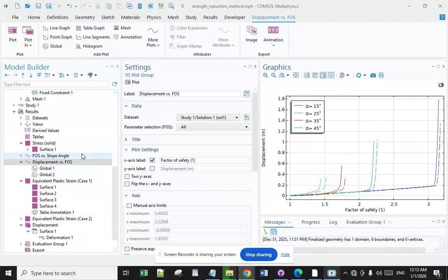Choosing design factors. Appropriate design factors are based on several considerations, such as the accuracy of predictions on the imposed loads, strength estimates, and environmental effects to which the product will be exposed in service, the consequences of engineering failure, and the cost of over-engineering the components to achieve the factor of safety.